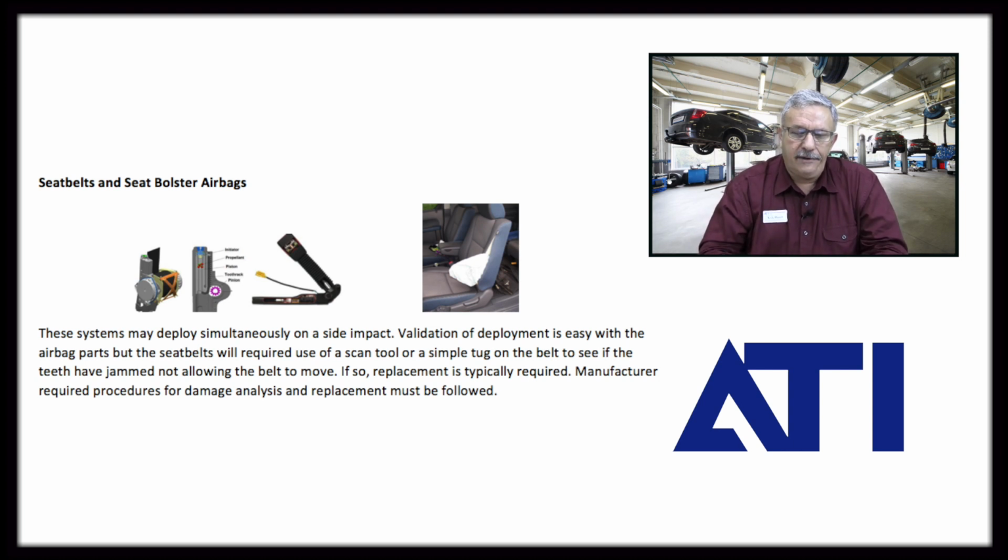One thing I do want to cover that I don't think is covered enough when folks do estimator, repair planner training is, what happens if the car goes underwater? So what are some of the things that you might want to look for? Remember that this part for these seatbelt retractors is going to be at the lowest part. That D-ring mounting area is at the lowest part of the vehicle. So it's going to be right in the B-pillar rocker area.